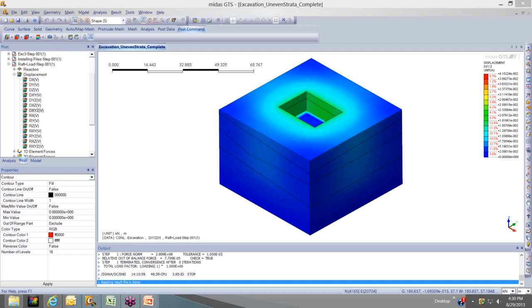Is it possible to import drill holes with lithology data or to import grid surfaces from other modeling software into GTS? Okay, so thanks for the question, Jeff. It really depends on the modeling program and the format that you use. The best way to import any type of geometry is through an Excel spreadsheet. And I know other programs out there have that same sort of Excel format.